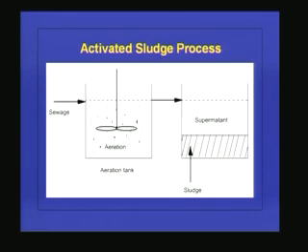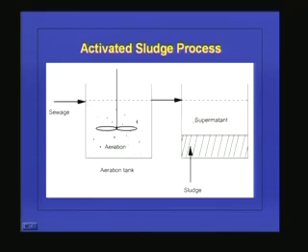These extracellular polymers have some binding property. Because of this binding property, what will happen? All these colloidal cells will aggregate and form flocs. Once they form the flocs, the settling will be very easy. So, in the sedimentation tank what will happen? The flocs will be settling and we get clear effluent and that can be removed.